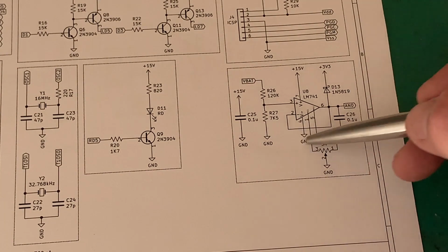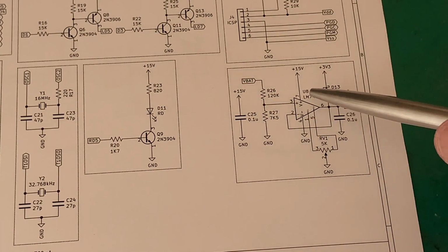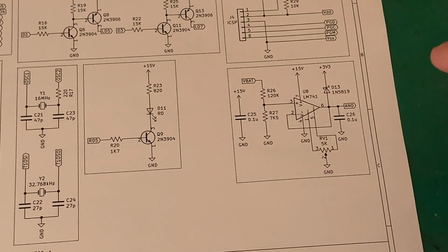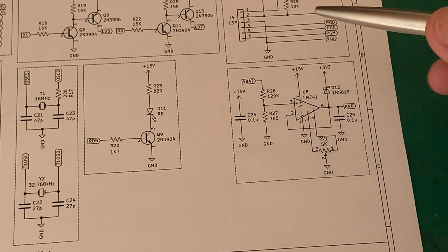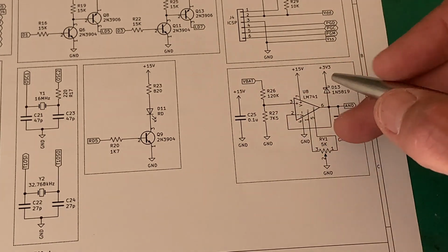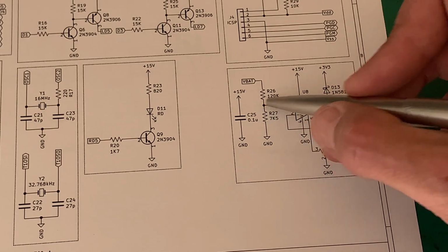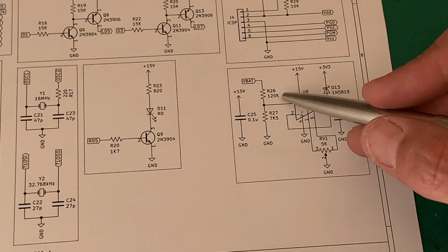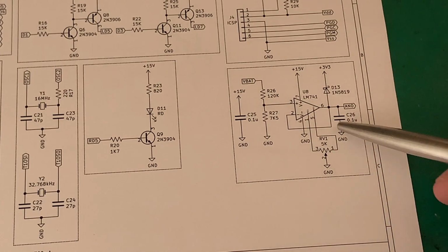So we're using this as a buffer, as we showed earlier on in our building blocks, in a real life circuit. First of all, to scale the voltage down to something that's usable. The op amp is not doing that, but the op amp is buffering or isolating whatever's happening there from here. So we can't get any huge amount of current flow into our micro.